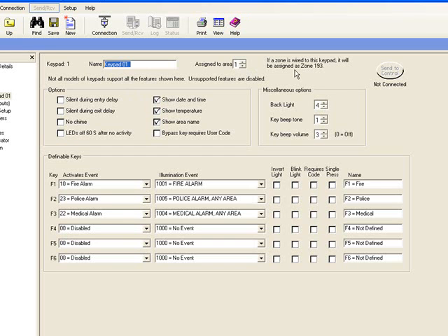This is actually talking about the wire harness hanging out of the keypad. There are 2 extra wires: a brown wire and a blue wire. The blue wire is an extra zone wire in case you need it. For keypad 1, this zone will be attached to zone 193. Let's say you forgot to run the wires to the side door, but you have a keypad there. Instead of running the zone wires all the way back to the panel, you could just run them to the keypad.